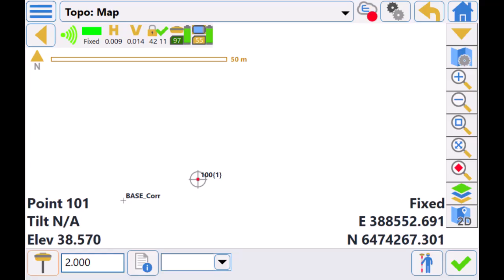For this feature to work, the user needs to store the point as the same name when taking any topographic readings. And this feature only works for an existing topo shot performed in this current job, not a point that has been imported. In this example, we are doing a weighted average on point 100.